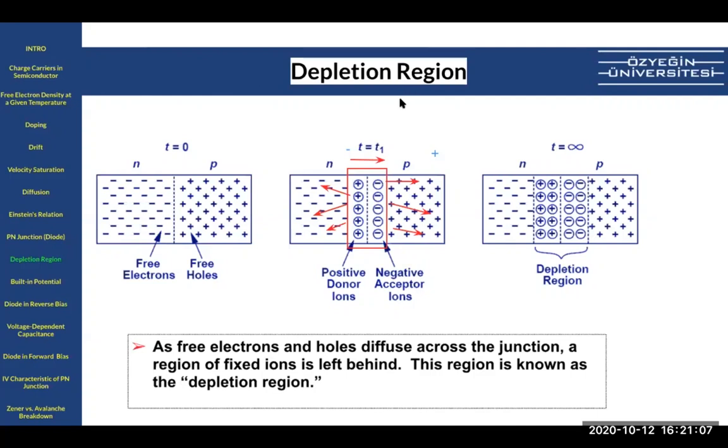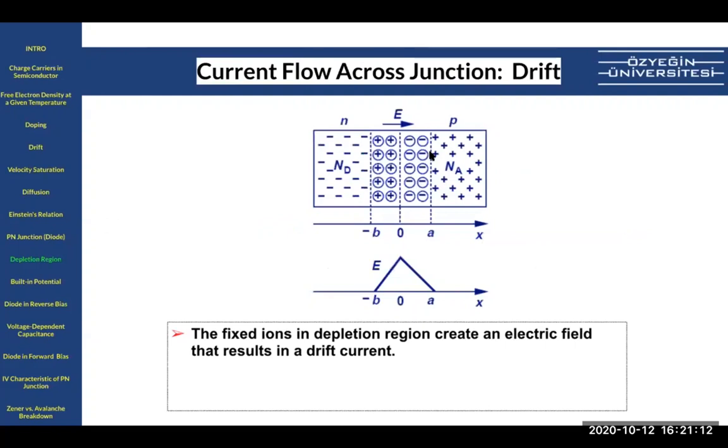So looking at the next slide, we will realize that this depletion region actually prevents the diffusion current at some point, because in the actual PN diode, these holes are more, right? They will want to flow here. And these electrons are more, and they will want to flow here, right? But they cannot, because this junction, as you can see, the pluses will push the holes away.